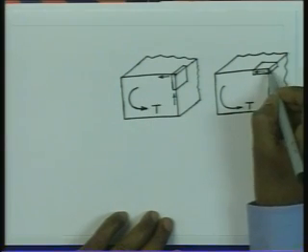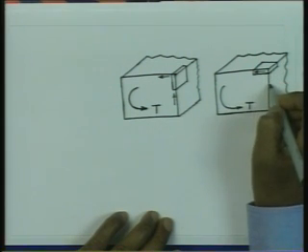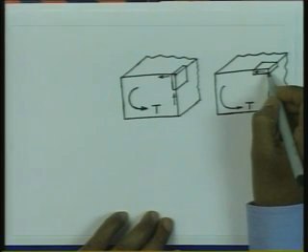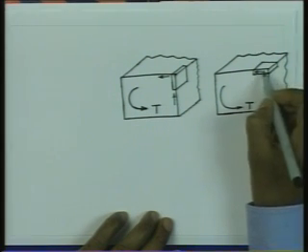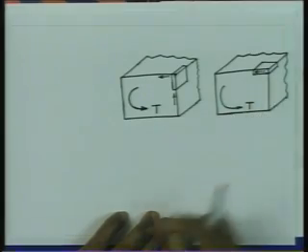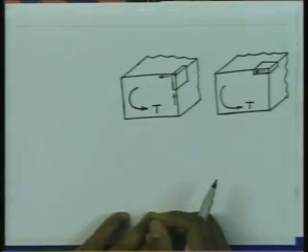Now, this stress, it is obtainable from the slope of the phi surface in this direction, in the perpendicular direction. Since phi is 0 along this boundary, therefore again the slope is 0, therefore this stress is 0. So, this is from the Prandtl's membrane analogy. So, we can find the answer that the corner stress is 0 from the uniqueness of the stress at the corner point, and from the membrane analogy.